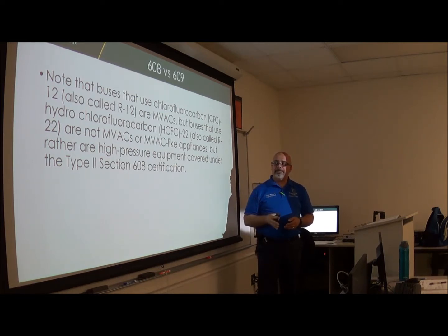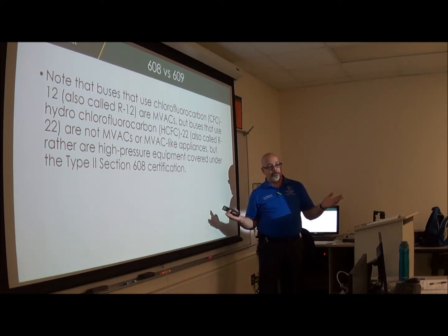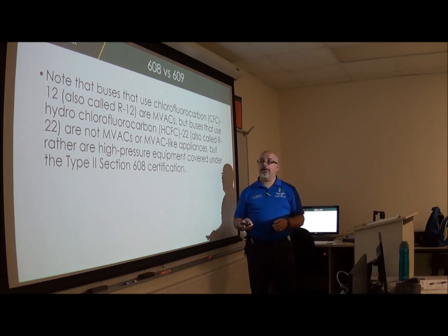The Section 608 test includes 4 parts. It includes the core, the Type 1, the Type 2, and the Type 3. The test will bring everything. If you want to concentrate on passing Type 2, you can do that, or not do anything in Type 3 and Type 1 and just answer Type 2, but the core, you have to pass the core. If you don't pass core and one of the levels, you're not certified in any of those levels. In this case, you would have to pass core and Type 2. If you take the whole test and you pass all 4 parts, you're certified universal.